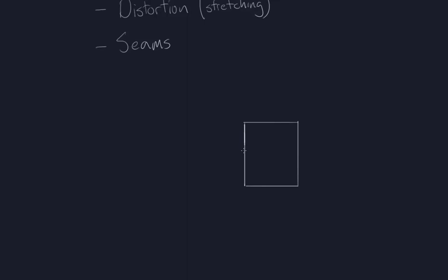Materials, like everything in Maya, but it's kind of a special case with materials, are all made out of nodes. You will have a node specifically for your material. We actually saw those just a second ago when we were looking at the Phong and the Blinn and the anisotropic, and so forth. When we were looking at all of that, we were looking at material nodes.